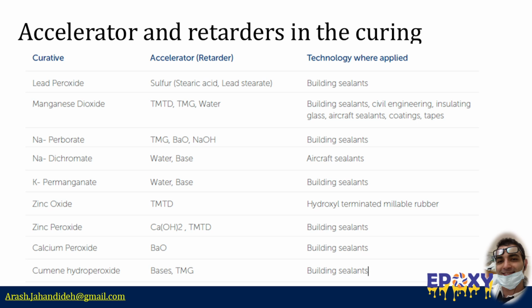In practice, amines and related basic components are commonly used as catalysts, while weak acids like stearic or oleic acids serve effectively as retarders. Interestingly, organic monomercaptans, though often added as chain stoppers to limit cross-linking, can also act as strong retarders, even at very low concentrations.